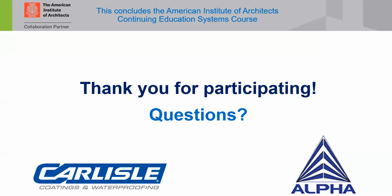Well, thanks for joining us, everyone, this morning. And Brian, I can't thank you enough. Case studies are always interesting. And as you're going through the slides, I can't help but put my building official hat on, and I'm thinking about how I'm reviewing the plans for this project, and frankly, how I would have some comments on, you really want to use rock wool here, but more importantly, as far as code compliance, looking at those intersections of the dissimilar materials and looking at the continuity of the air barrier.